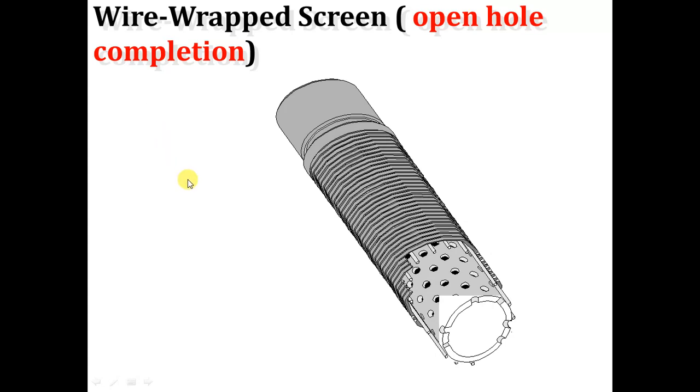Now we will make open hole completion. So after pulling out of hole with the cleaning assembly, or slick assembly, we will run in hole with the completion. It is screens, because it is open hole completion. We are running with screens, wire wrapped screen. So before pulling out of hole, we have to be 100% sure that the solids percent in the mud is very little, in order not to plug these screens.